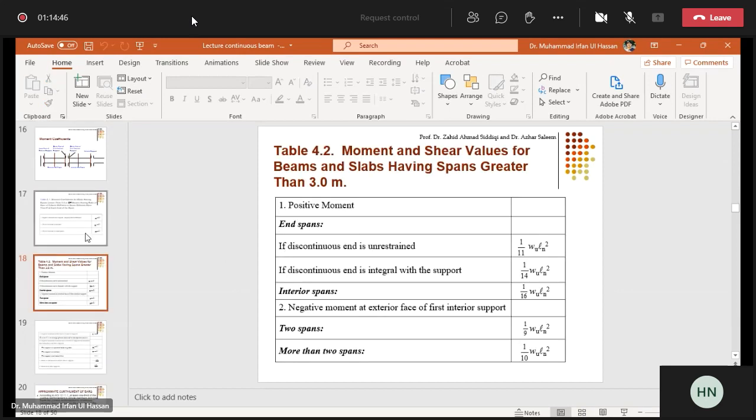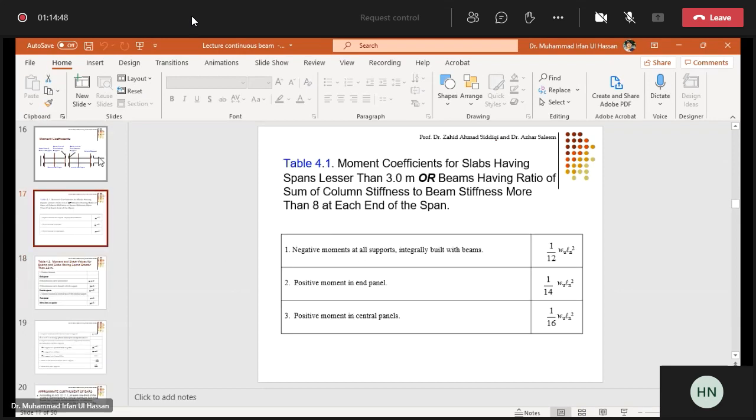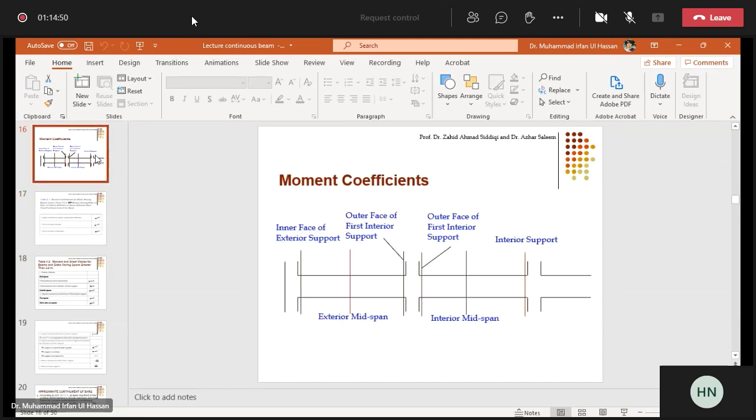So basically it can be any kind of beam, either singly, doubly or T-beam. Mostly it can be like a T-beam in the mid span, and also an inverted T-beam at times, when there is compression at the support. The compression is at which side? Bottom side.